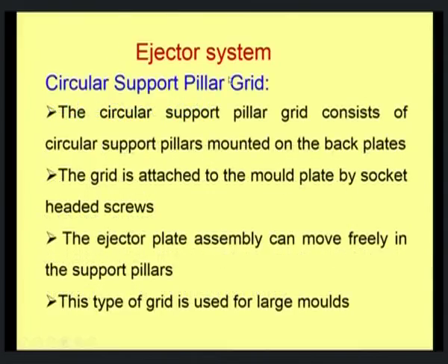The circular support pillar grid consists of support pillars in a circular fashion mounted on the back plate. The grid is attached to the mold plate by socket headed screws. Therefore, a socket and screw arrangement is provided.